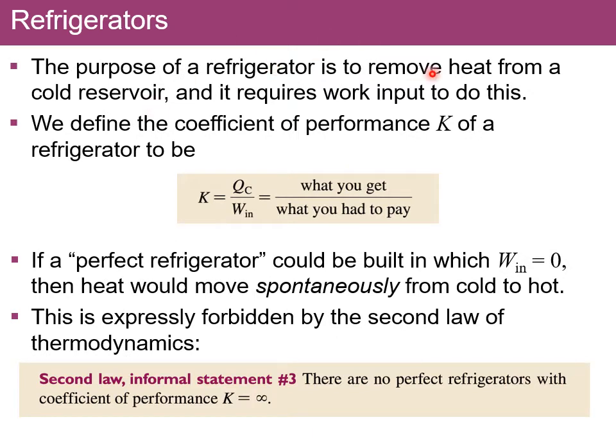The purpose of a refrigerator is to remove heat from a cold reservoir, and it requires work input to do this. We define the coefficient of performance K of a refrigerator to be equal to the heat extracted from the low temperature reservoir divided by the work input into the system. Since heat does not flow from a cooler system to a warmer system of its own accord, there is no such thing as a perfect refrigerator in which K tends towards infinity.